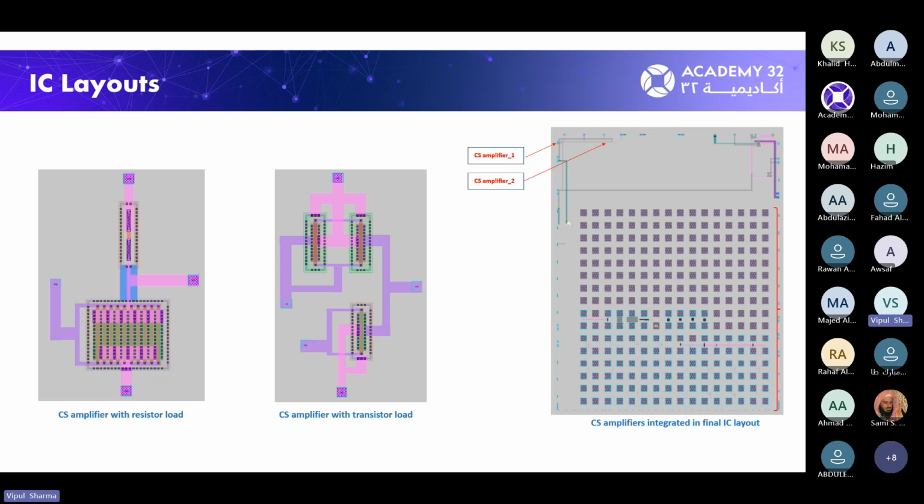And this is the benefit of VLSI and IC technologies, which we were discussing yesterday. If you had to design a similar circuit on a PCB, you can think how many things would be required. First, you have to take a discrete transistor in a package format. Then you have to take a resistor and put it on a PCB, solder it. Then the PCB itself will have some size, but everything of that sort is accommodated in such a small area. It might be just 100 micrometers or even less than that. So these are the benefits of VLSI technology.